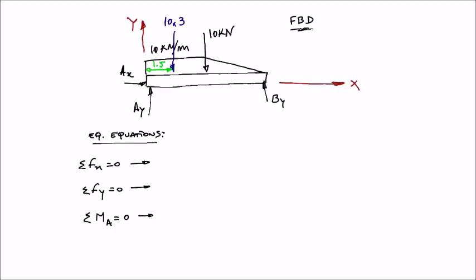We are going to do the same for this triangular distributed load here. I'm going to replace this with an equivalent force located at the centroid of this triangle.